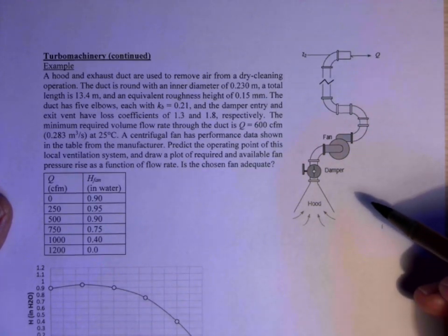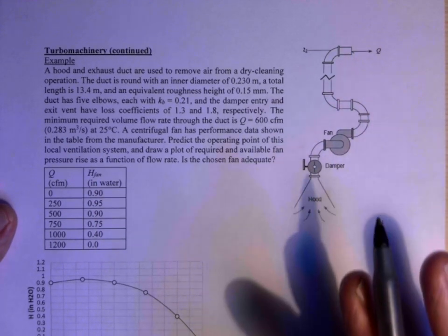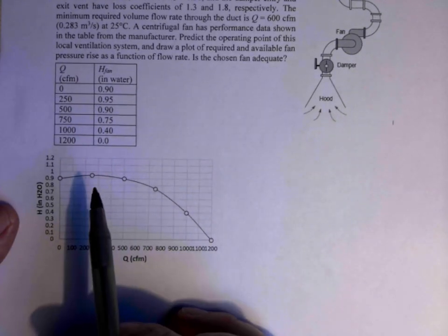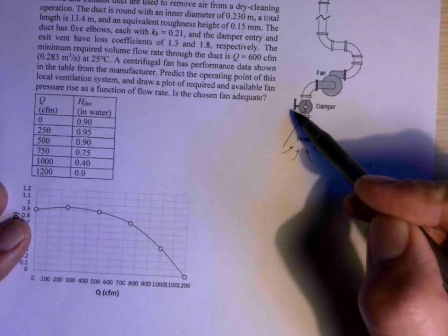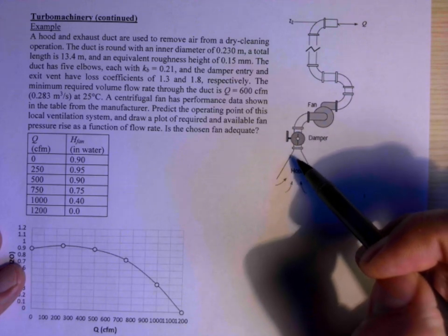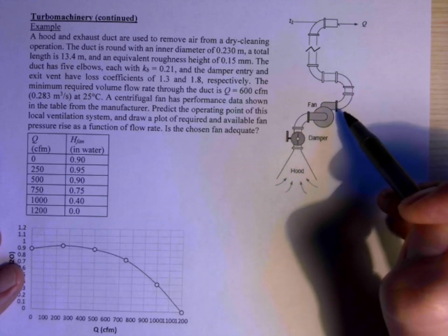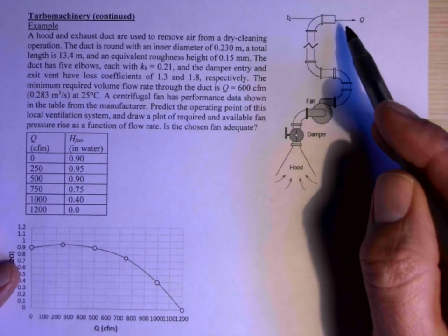So it's really the same kind of idea, but it's good to see a different fluid to understand how that's different. With pump curves for water, you have a pump curve given by the manufacturer. With air, you have a fan curve. So here's an HVAC system schematic that we're looking at. There's air that's pulled in here, and there's a fan that's pulling the air through and then discharging it over here. And we want to know how much flow we're going to get.